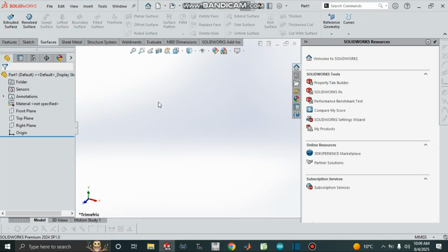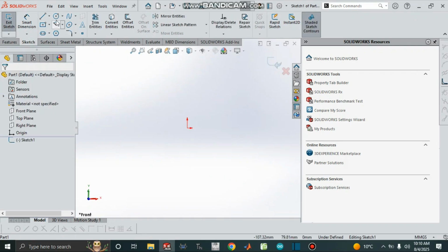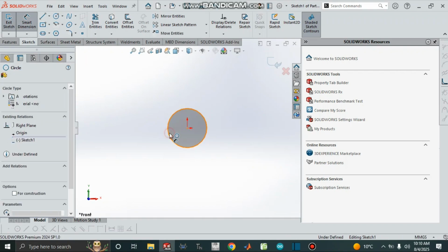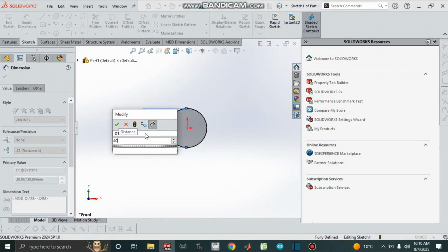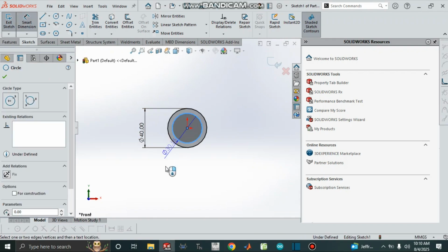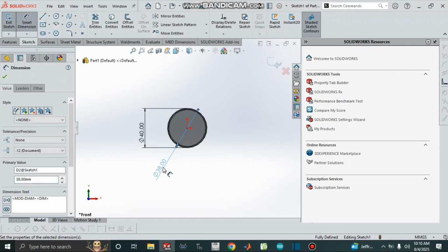So the screw diameter is going to be 150. Then the standard length is going to be 3050 millimeters. Then for the shaft, 40 outer diameter. So let's model this shape. We begin with the shaft diameter. Let's put 40. Let's make the shaft hollow, so let's put 38.